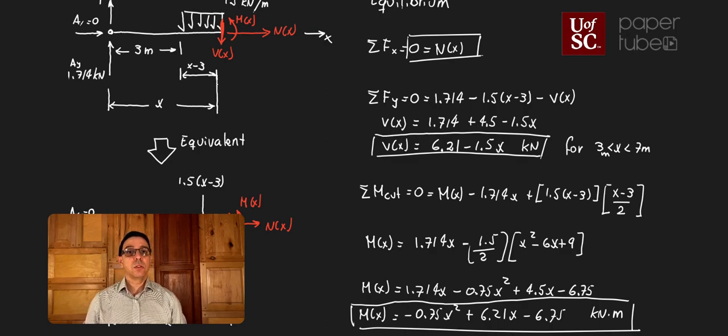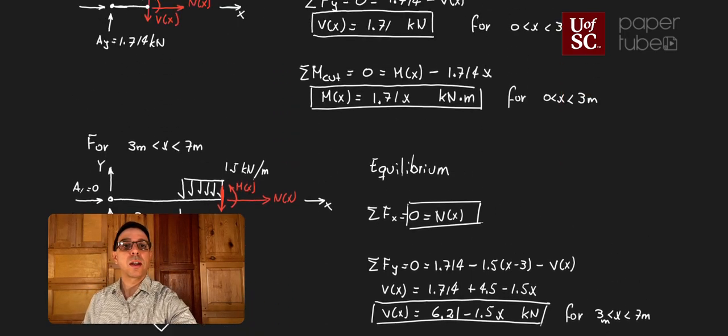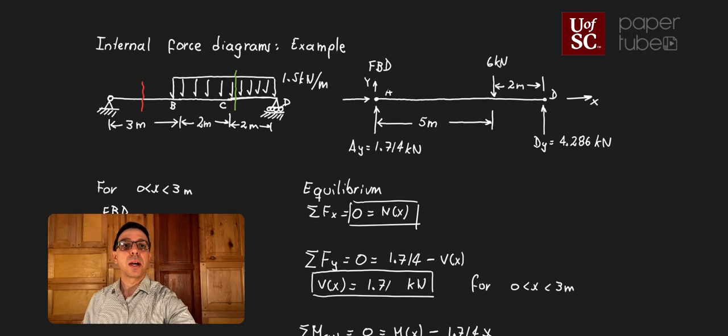Now what I want to do is see how can we plot this. And let me find another piece of paper here. So what I'm going to do is an XY axis, where my x is the same axis as in my free body diagram up there. My y now is going to change. For one diagram it is going to be my normal force, for another diagram my shear force, and for a third diagram my bending moment. So let's just start with that.